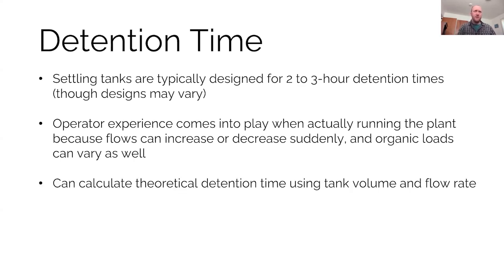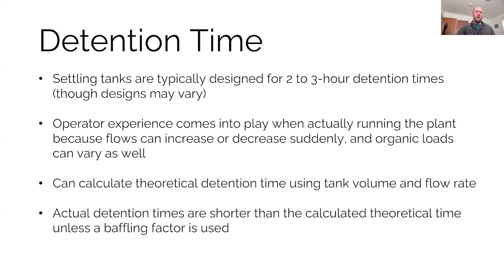And then, like I talked about, you can calculate the theoretical detention time with your specific scenarios and compare different times, like what happens with your flow during your peak flow hours versus at nighttime. So you can figure that all out. The actual detention times are smaller than what you calculate based on your tank.